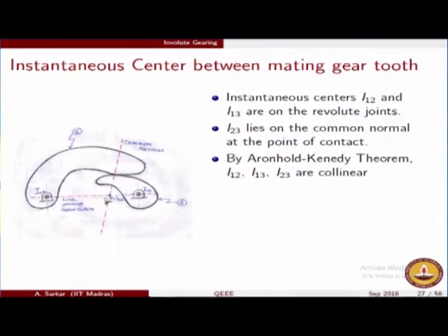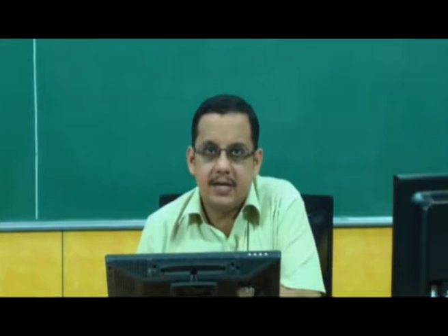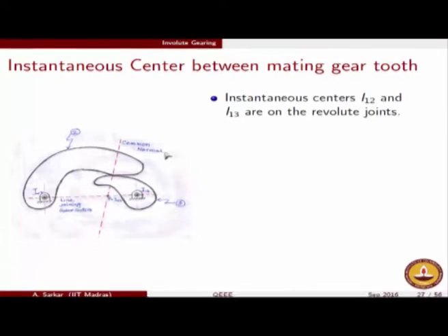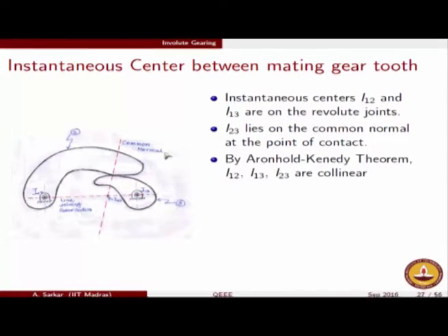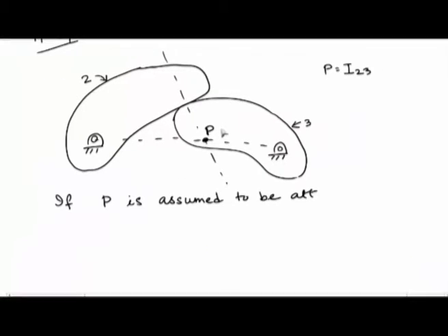So DGI is asking which profile of tooth should be preferred. The answer is involute. Already we have seen one advantage of the involute, that being it is conjugate. So as Mr. Ujjwal Rane also said in the animation, an involute teeth profile on one gear meshes exactly with the involute tooth profile with the other gear. And also satisfies the fundamental law of gearing. So this is a very important advantage. So this is not true for an arbitrary gear tooth profile.